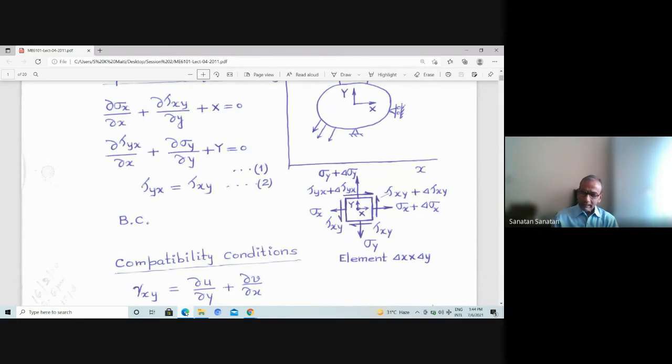How was it done in the case of strength of materials? Even if you consider, let's say, the problem of a propped simply supported beam, one end is fixed, the other end is just simply supported, then we have to find out two vertical reactions at the two ends plus the moment. So therefore three unknowns. So what we do is we try to find extra equations to overcome this statical indeterminacy. What is that extra equation? We have to bring in the deformation condition in some way to bring in another extra equation.